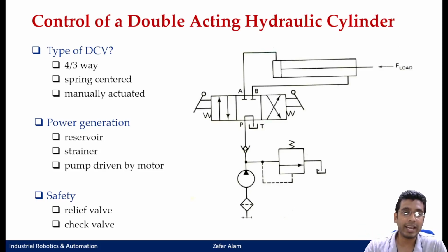Okay, so in that case, again, your check valve, even if the cylinder is only half extended or 3/4 extended, and then there is a power failure, it would just try to hold the cylinder in that position itself, because the fluid, while trying to come back from this line itself, your energizing port, will not be able to flow in the backward direction. Okay, since the check valve only allows a flow through one motion, that is from, in this case, bottom to the top. Okay, no flow can be allowed from your top to your bottom. So this also acts like a safety device.